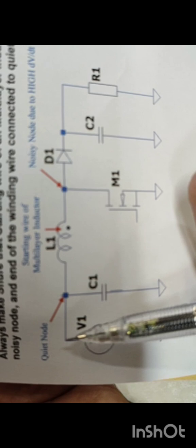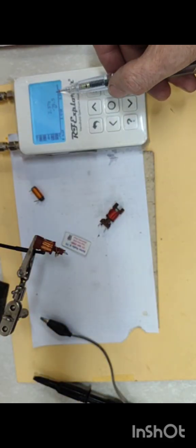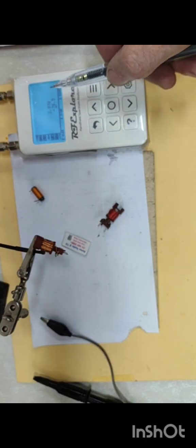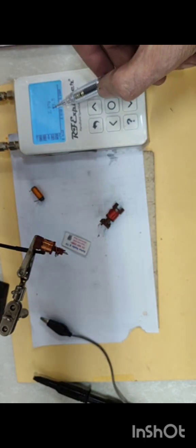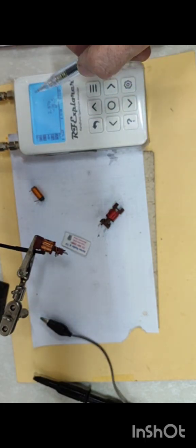So we've got positive applied over here to the coil, and with this MOSFET, this inductor is like a buck converter, keeps on switching this side of the coil to the ground. But it happens very fast, and in this particular case, I'm using 2.9 something, 2.973 I see on the spectrum, 2.978 megahertz.